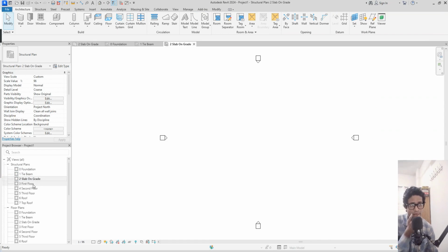link the CAD files. I have already shown you the CAD files. Actually, you have two options in your hand. Either you can link your CAD file, or you can import your CAD file. And there are some major distinctions between importing and linking, because when you are importing a file, you are literally inheriting all the elements from that imported model to your host model.